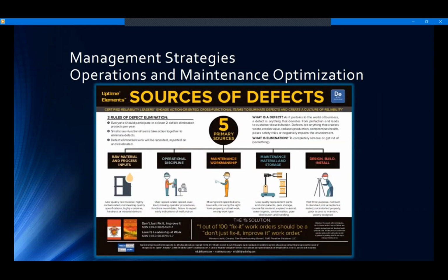Defects that affect our optimization, and the sources of these defects. We have defects from the quality of materials, defects from workmanship, defects from failure events, defects from design, and defects from operations. Many defects ultimately lead to failure. They're either introduced through operations or detectable by operations long before they will cause a failure. Think of a cavitating pump or ignoring excessive vibration in a pump.